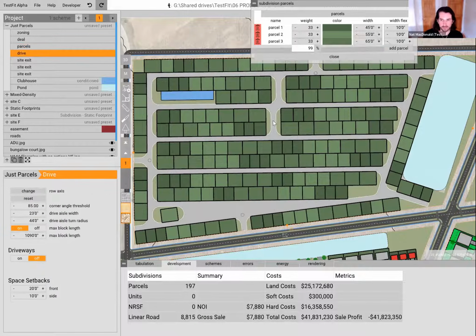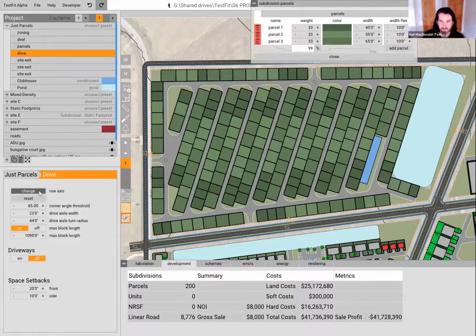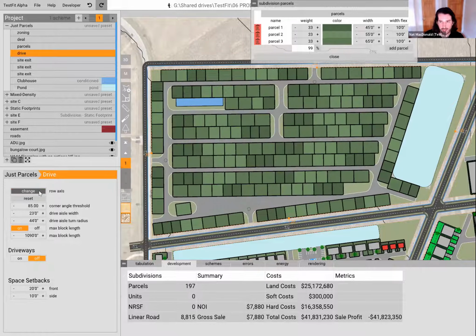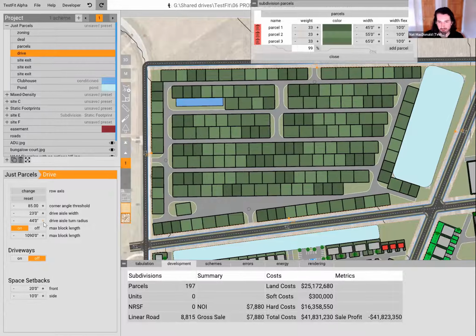Okay. So first thing we can talk about is how we lay out our road network in this. Basically, we're going to generate this, and then you can edit it to your ideal road, but you can generate different options. Based on different road axes, we have typical parameters that you can adjust, like width and radius.